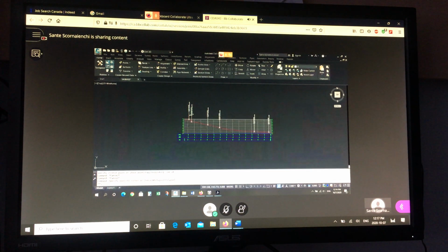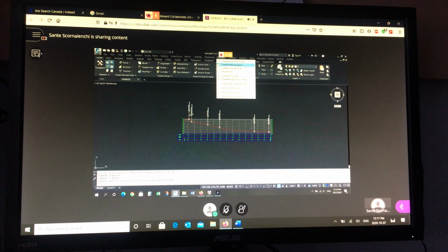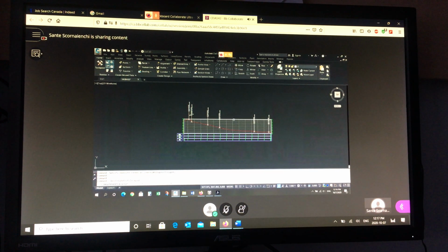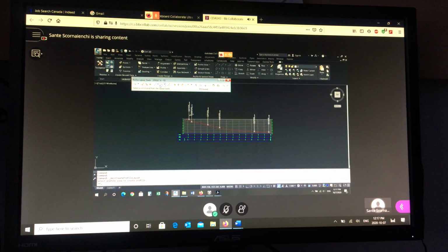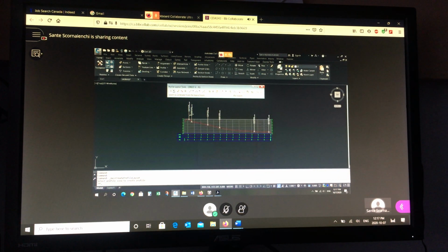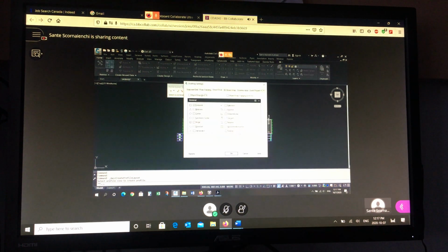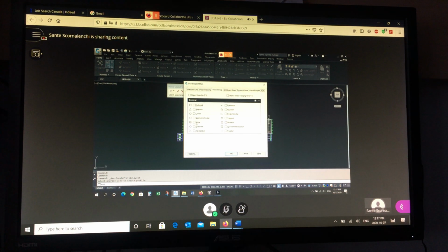Okay, so we're going to go to Profile, Create by Layout. This is a bit of review from highways. You're going to pick the grid. I want to do my design in here. I'm going to give it a name. I use the repeat street X, that's the horizontal street name, and then I say finish ground FG. When I say OK, I get this dialog box. You might recognize this from highways. And then it's not the first button, but the second button. And now you want to set your O snaps before you start. Set your O snap to clear all node, because all those points are nodes. Say OK.